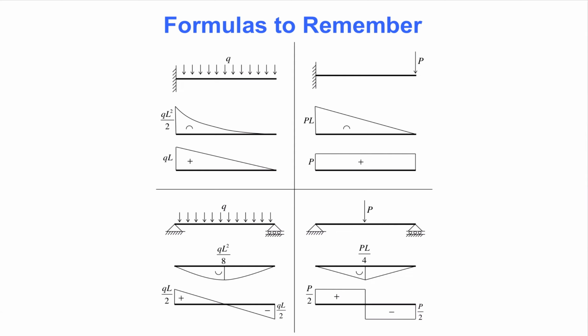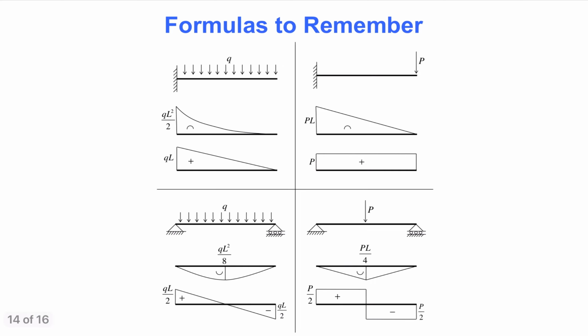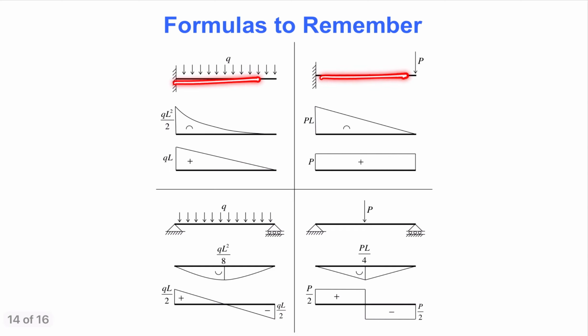We will establish bending moment diagrams first, and we will do that for a variety of frames and continuous beams. When we are doing that, it often saves time to be aware of the basic cantilevered and simply supported beam cases shown on this slide. Notice, the bending moment at the base of a cantilever with uniformly distributed load is QL²/2.